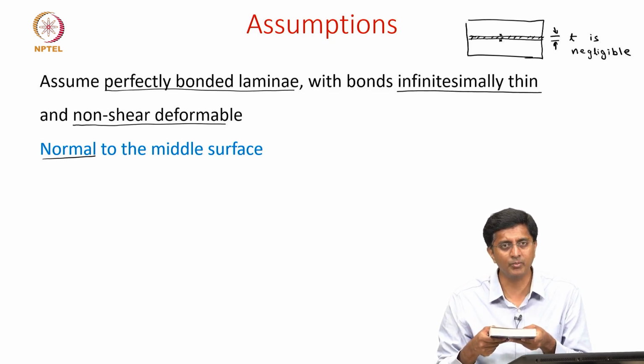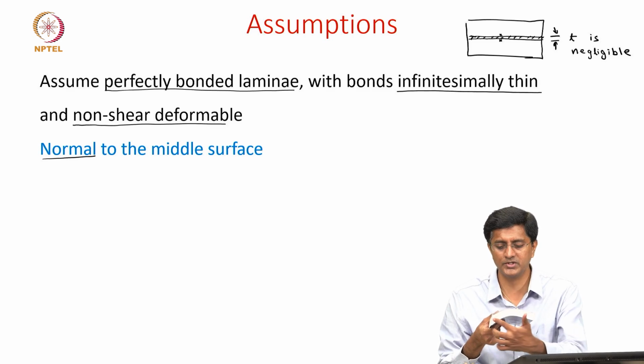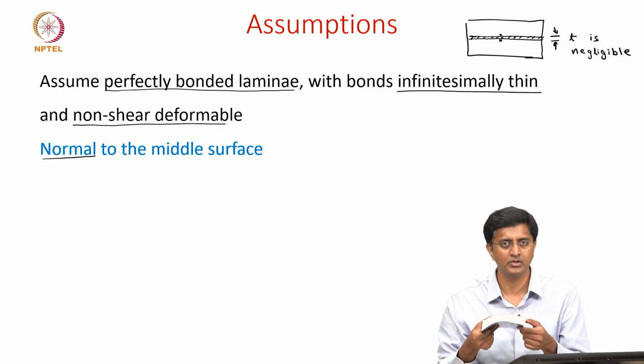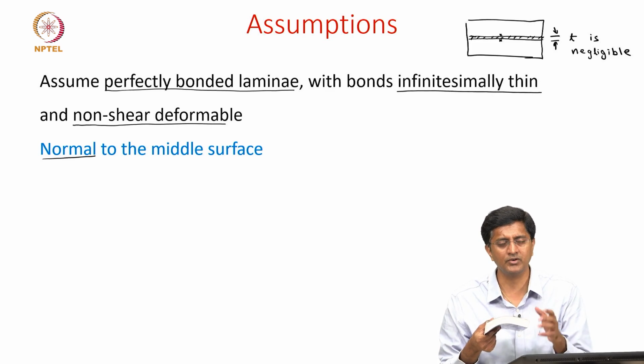Now let's see what happens to these two normals when I deform or bend this book. When I bend this book, there is a stark difference between how this edge deformed versus the other edge deformed. Can you notice what the difference is? Are these both straight lines after deformation? More or less the answer is true. So this is straight after deformation, and even this is more or less straight after deformation.